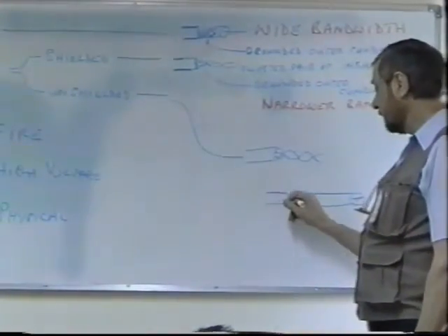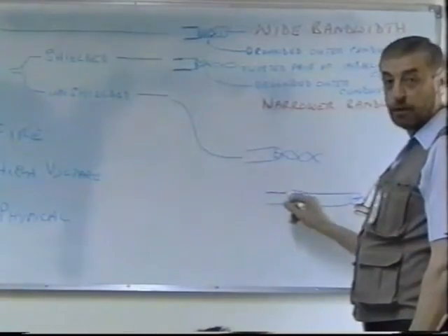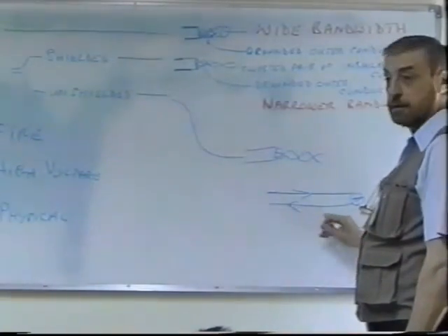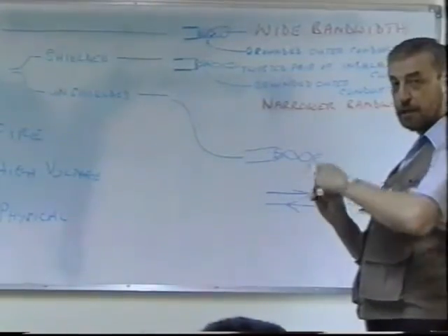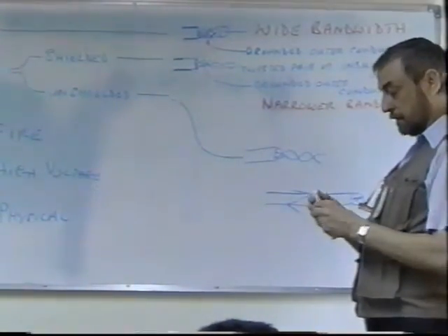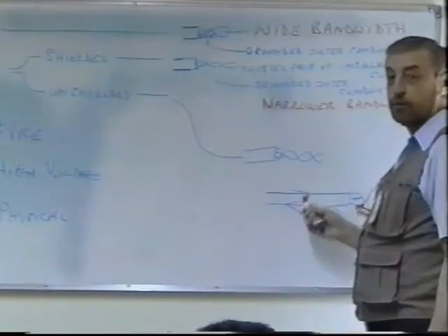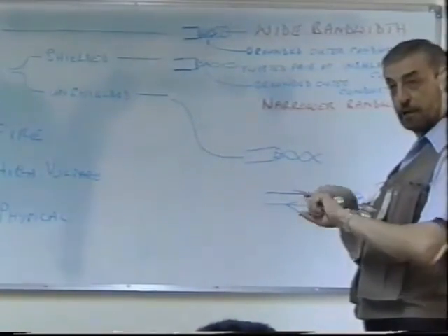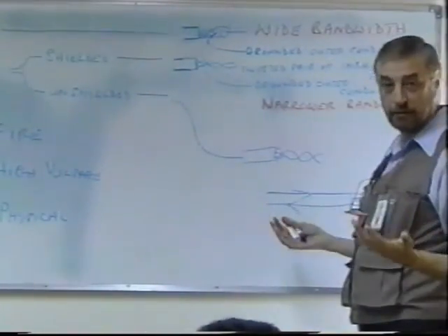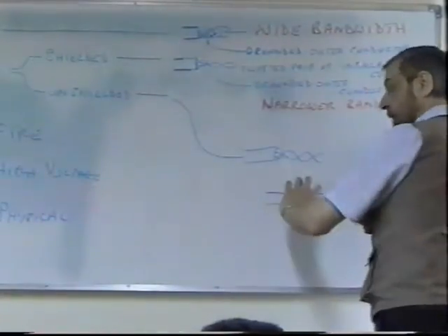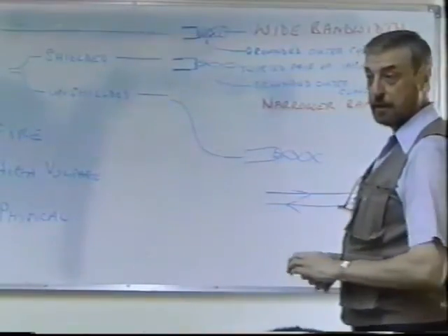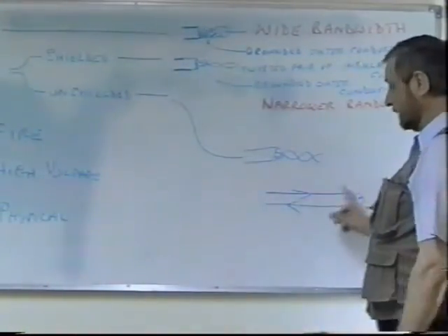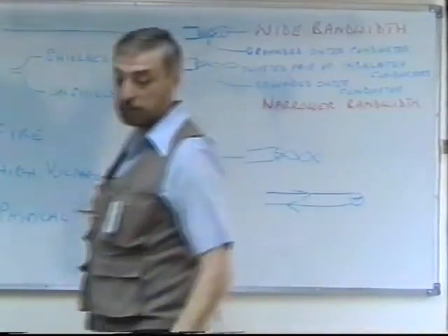So the magnetic field generated by one current will be cancelled, because this current's in the opposite direction, by the magnetic field in the other. By twisting them around, you make sure that the magnetic fields cancel one another, so you don't get any interference. And similarly, any noise coming from outside is cancelled within the twisted pair. So that's the reason why they twist them around.